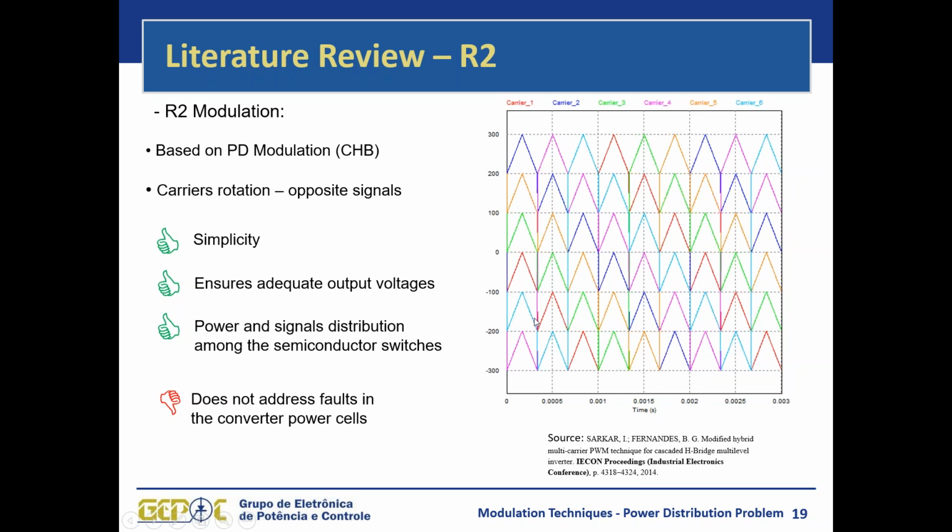So in this sense, we also have a simple implementation that also has a very good harmonic performance, and also regarding the output levels of the voltage. We will have an even distribution of power among the cells and among the semiconductor switches. But it also does not address the problems of faults in the power cells, on the inverter power cells.